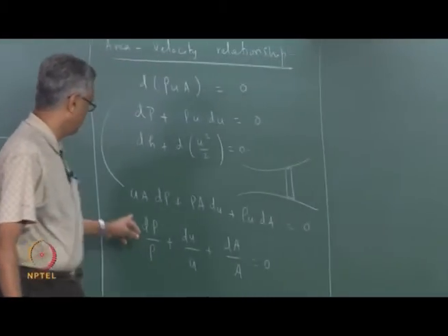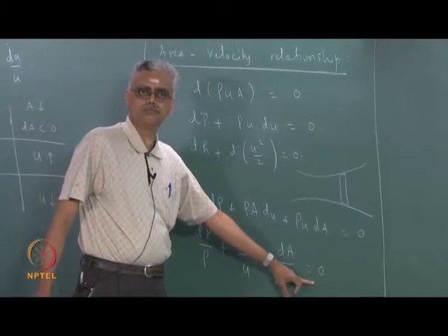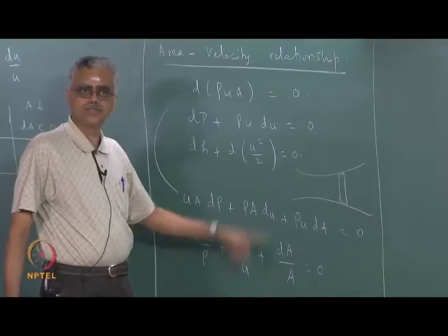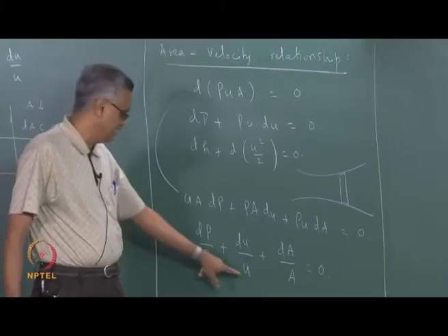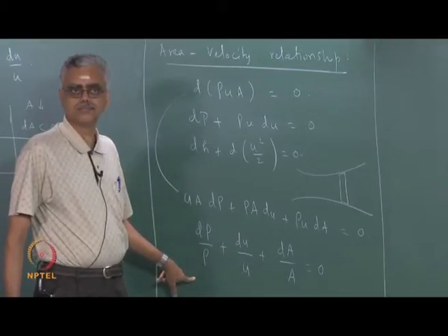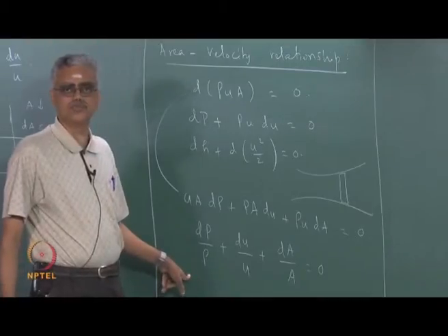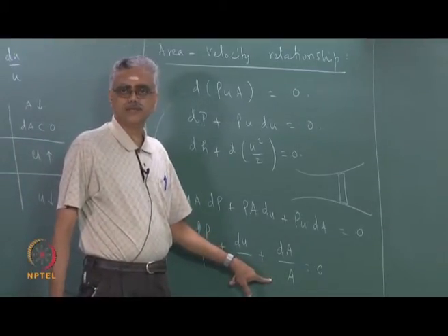So now if I use that information in my continuity equation for mass conservation, this sum must always be equal to 0. So this has increased slightly because I said du was positive. Now this has become negative but less than this. That means for this entire equation, left hand side to sum to 0, what should dA be? dA should be negative, right.